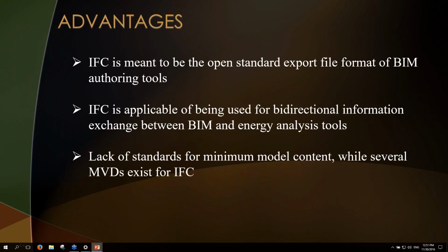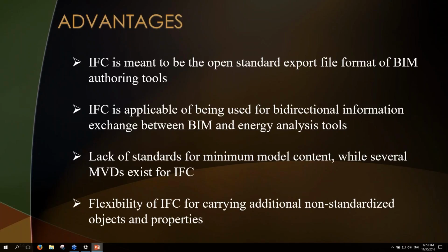MVD: one of the strong points in IFC is the capability for standardizing representation of information by developing MVDs. We don't have such things in other open standard file formats that exist for engineering analysis. And IFC is very flexible for carrying additional non-standardized objects by means of property sets. We can extend it. A user can extend it.